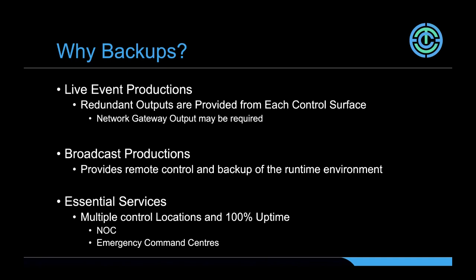In the days of CBC gone by, CBC used to have an actual physical A/B switch, if anybody remembers computer printer switches, where you'd flip the rotary knob and it would actually move 6 universes of DMX between the 2 physical console outputs. With the advent of networking and ACN gateways, whether it be Pathways gateways or our gateways, we would want our outputs to be native on the network. We want them to be streaming ACN or ArtNet gateways on the network.